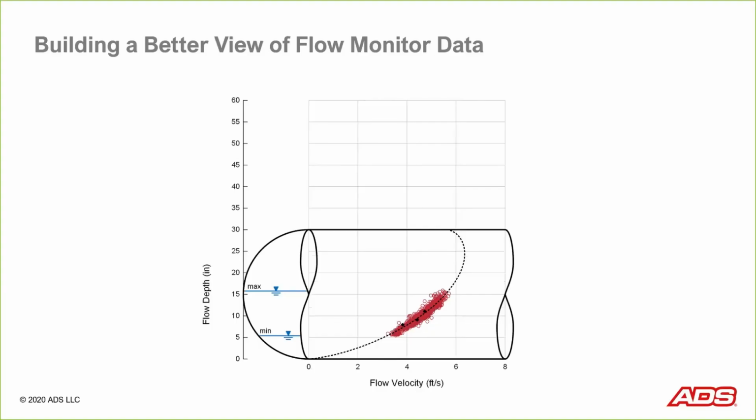So now instead of being depth to diameter ratios and velocities that are based on a full pipe velocity, I'm just showing you absolute numbers here. So you're looking at a scattergraph of a 30-inch diameter circular sewer, and you see the actual velocities plotted on here. And right off the bat, you see the fact that this data is in good agreement with the Manning equation.